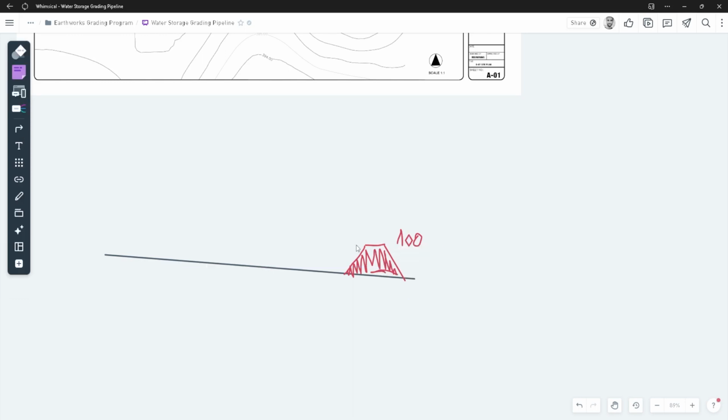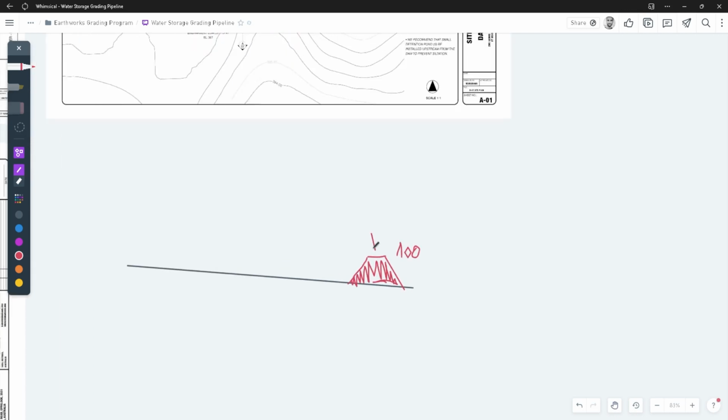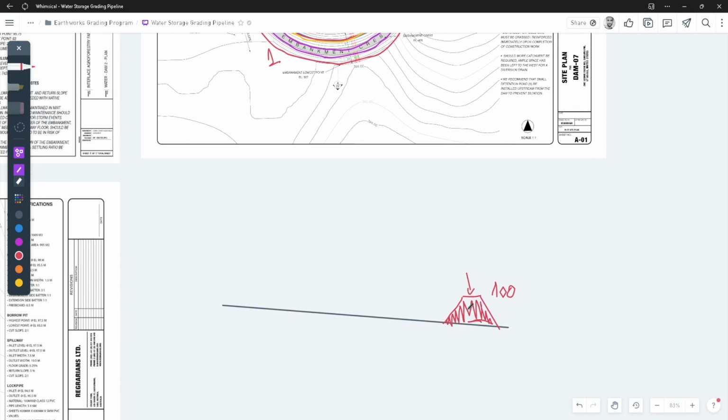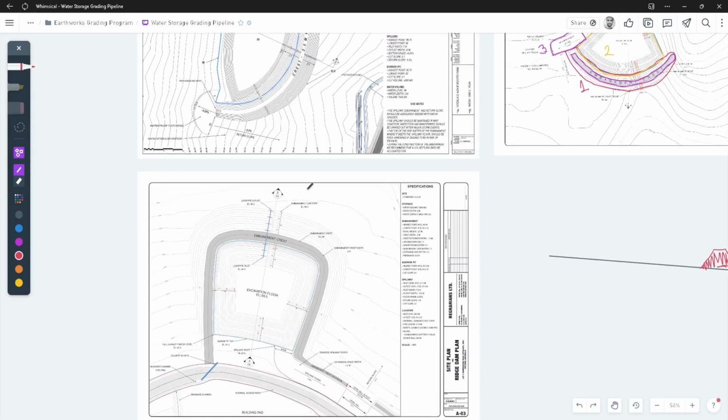But it's one of the first mistakes anybody will make: they forget to fill the structure with material, which is going to throw off any volumetric values that derive from it. So during the course of the program, I will always remind you that we need to infill the crest, or infill another structure, because otherwise it's going to be empty. I just wanted to throw that small detail in there.